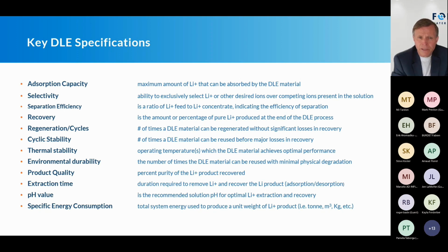But when you do that, just think, the higher the temperature I go, the stability of the material may degrade. So something operating at 20 degrees C, let's say, gets 2,000 cycles. If I increase the temperature, the stability isn't there, and I may only get 1,000 cycles out of it. So that's a critical component. Evaluating that, if I play around with the temperature, maybe I can impact my life cycle costs, meaning I'll replace the resin at a lower frequency.